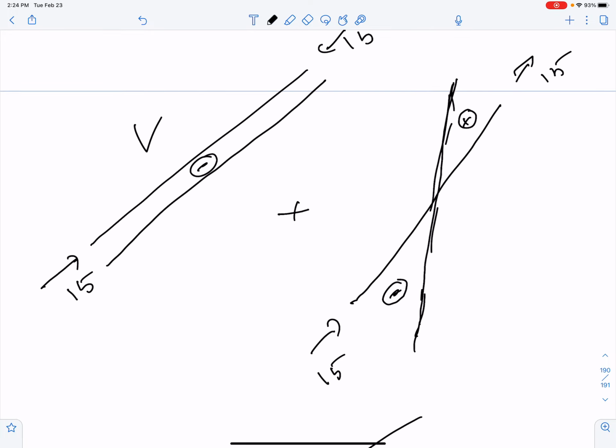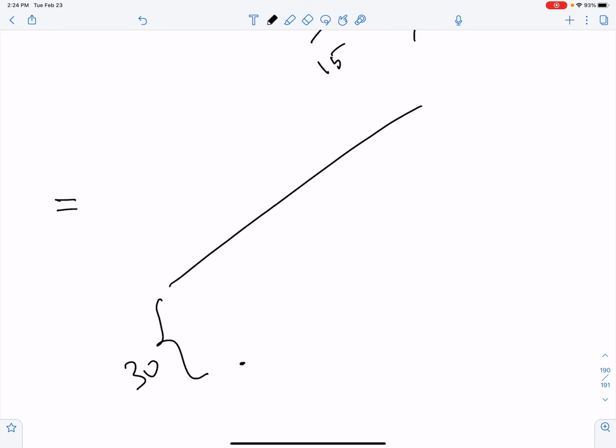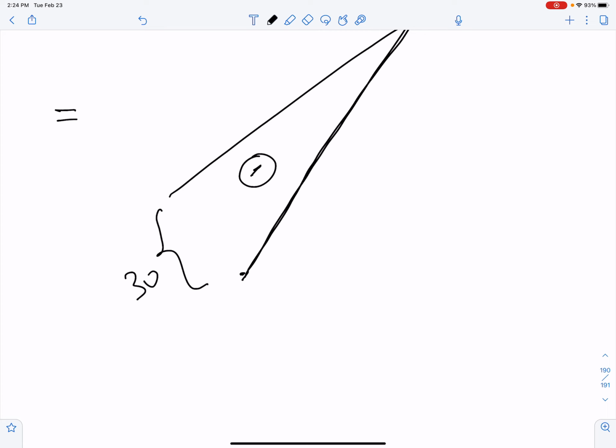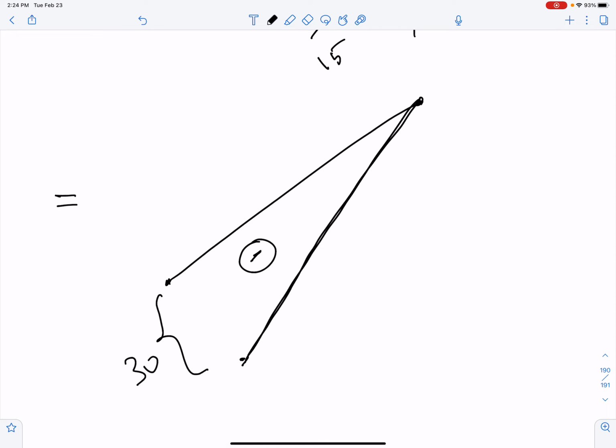And here, negative 15, positive 15 cancel. Okay, so the forces go to zero there. Okay? And it gives you this final axial force diagram, where you have a state of compression on the entire element. It starts out with 30 units of force at the base, and linearly decays to zero. Okay?